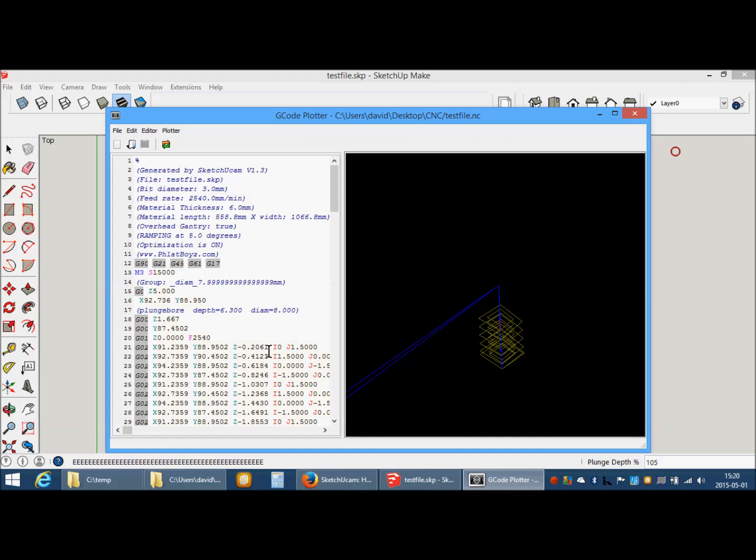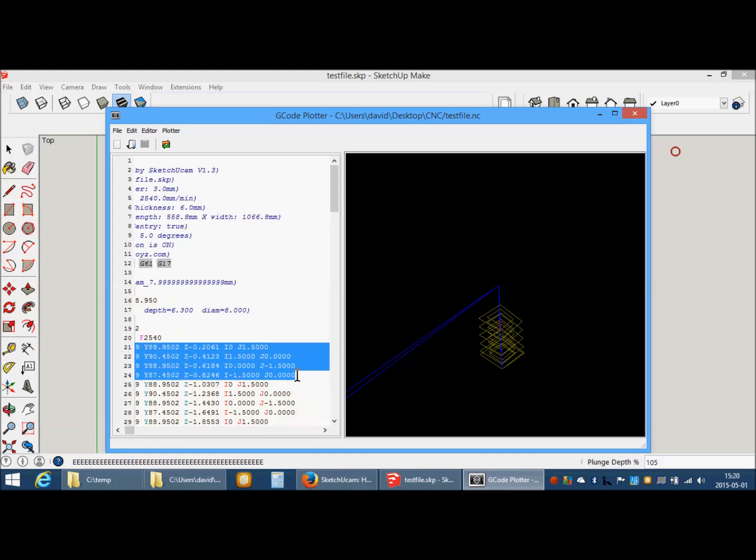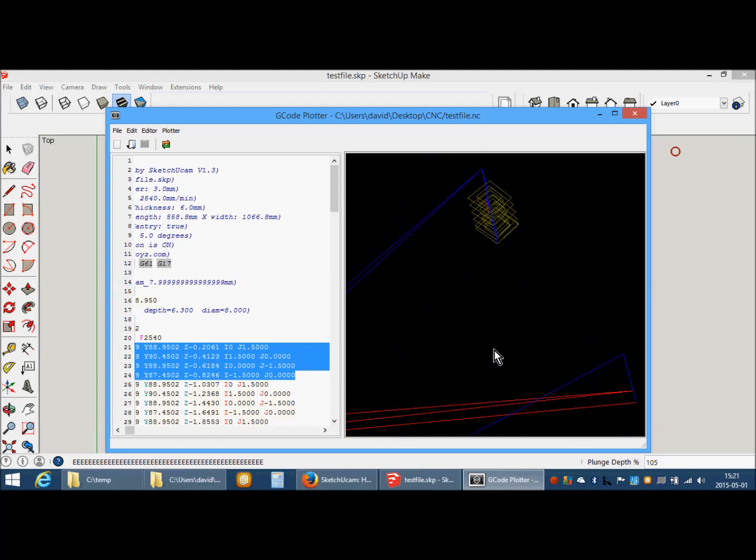As you can see in this code, that is a complete circle to that depth, and so it goes. So you can see it has bored that 8mm hole without a central plunged hole. It starts with a 2 times bit diameter hole, helically bored, and continues with the final